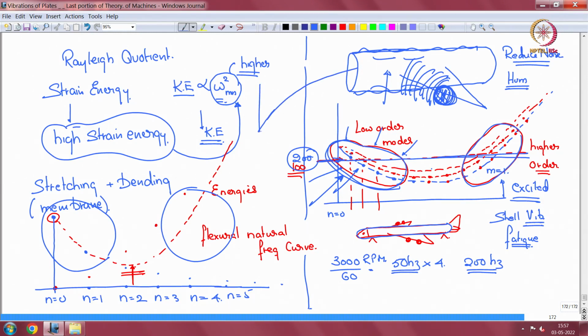They do not go through a dip if you plot your natural frequencies for a plate. They do not go through this dip, it is a flat structure. So I just wanted to mention how this dip creates a problem with respect to noise control in aircraft cabins.